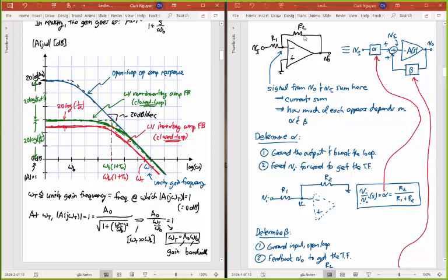Okay, but this is still a very useful amplifier, right? Nevertheless, because it inverts, whereas the non-inverting amplifier doesn't. And a lot of times we need that inversion, and a lot of times we want that inversion, and we care more about that than just this little reduction in our gain bandwidth product. So still a very useful amplifier, one of the most used amplifiers around. The other nice thing about the inverting amplifier is you really have this virtual ground at this minus terminal, so you can knock out a lot of capacitance for that device.